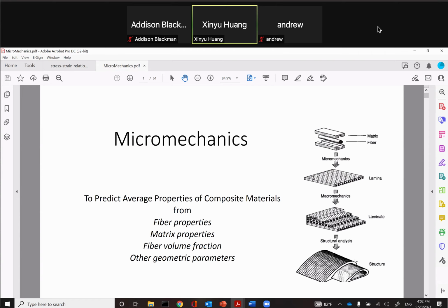Particularly material engineers, the people who make these materials, can use this to guide their material selection. Let's say they want to achieve certain properties. They select a glass fiber, nylon fiber, Kevlar fiber, or carbon fiber. If you know the theory, you can roughly estimate. Let's say you can put in roughly 40% fiber. You can use an epoxy-based matrix.